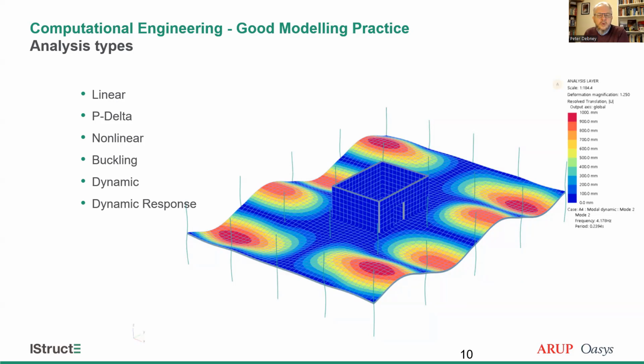Now, also, when you come to dynamic analysis, maybe things like the end connections might be different. So for a steel frame, typically moment releases on the ends of the beams, but for, say, a footfall analysis or a buckling analysis, you might be assuming they are fully fixed. So a slight difference in the model, and likewise for vibration. For footfall analysis, you might have cladding around the outside, and that would actually provide a restraint.